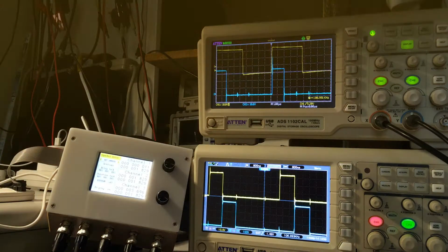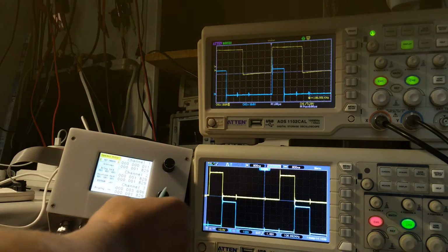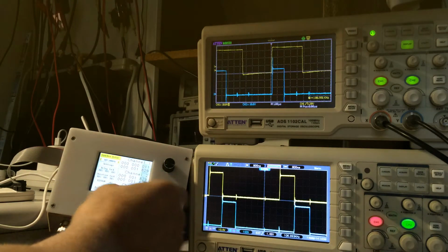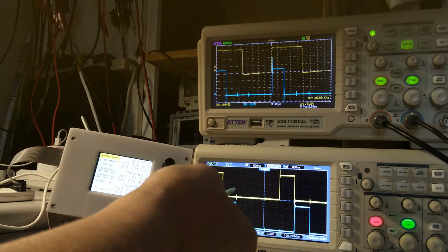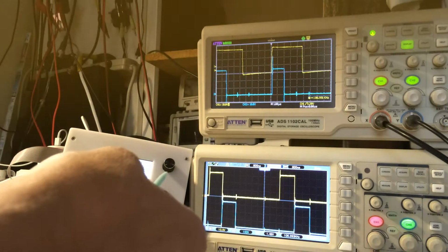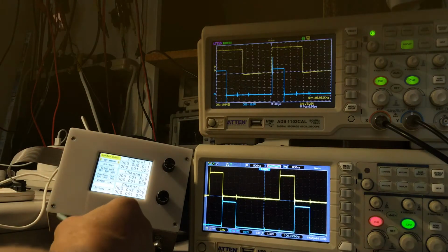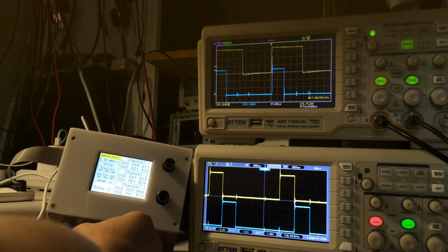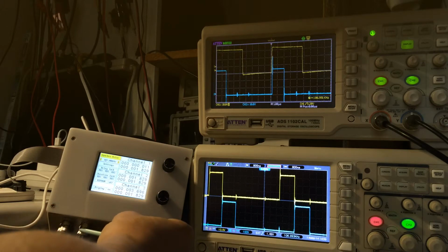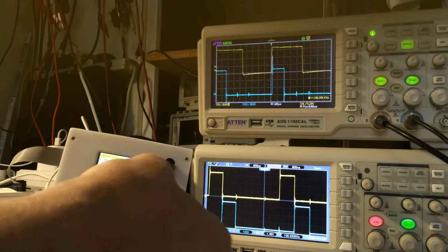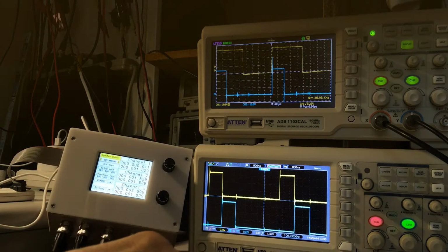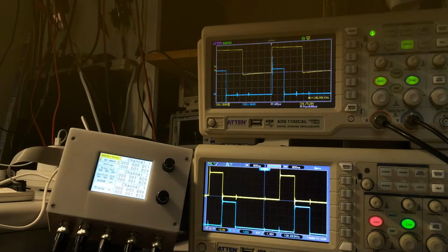My device can be managed in two ways. First, two encoders. By these two encoders, you can totally control all the parameters. But additionally, we have touchscreen functionality. So you can use touchscreen plus encoders or just encoders. About connectors, we have three output connectors, one separate output connector for the DDS source, and one connector input for the external signal. Now these two are linked. I mean, the output source for DDS connects to the input source of the synchro signal of 3 channels.